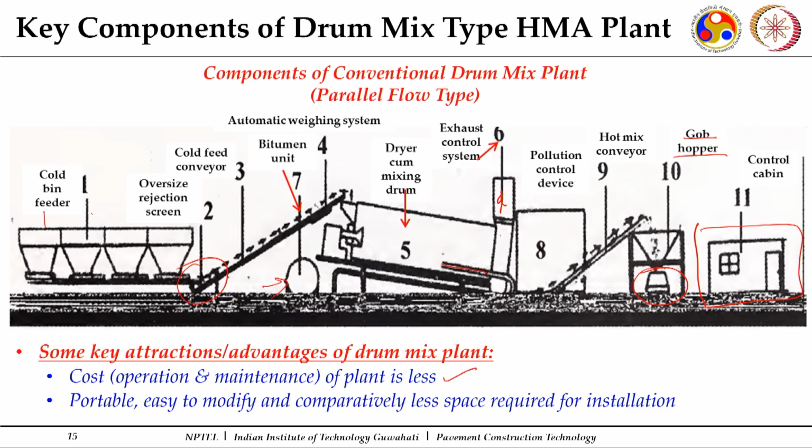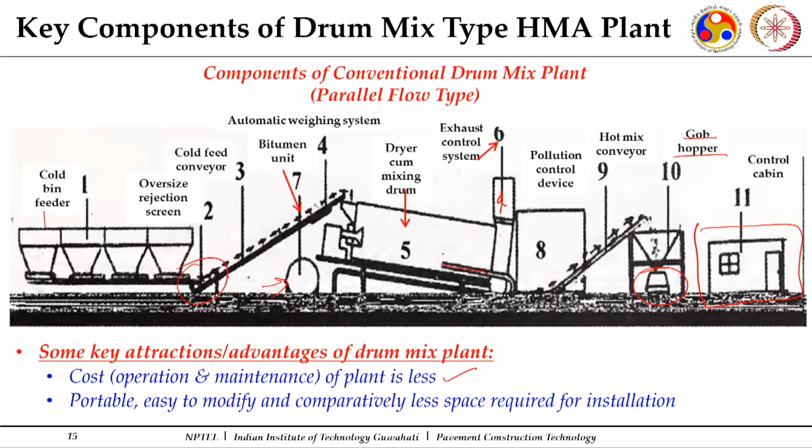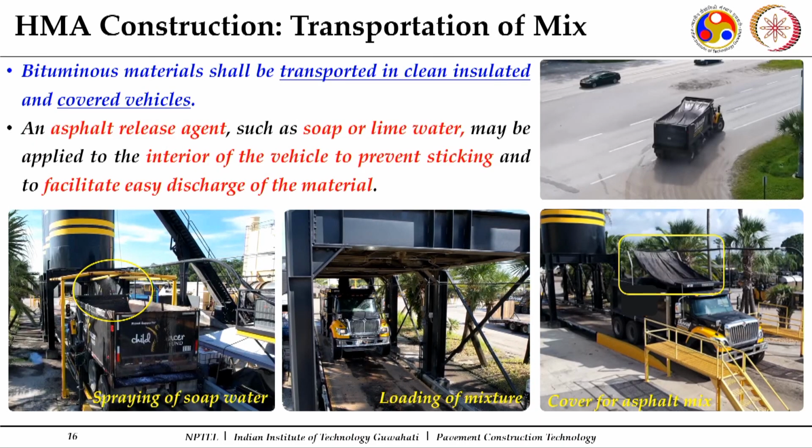It is easy to install and portable, and easy to modify. As I mentioned, in the case of introduction of reclaimed asphalt pavement, some modification may be required. That modification is more frequently done with a drum mix plant. Once the mix is produced, it needs to be transferred.